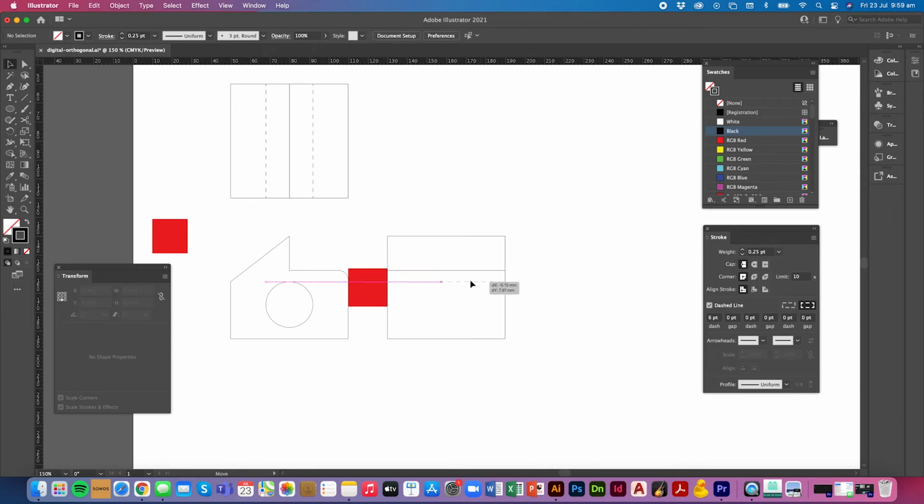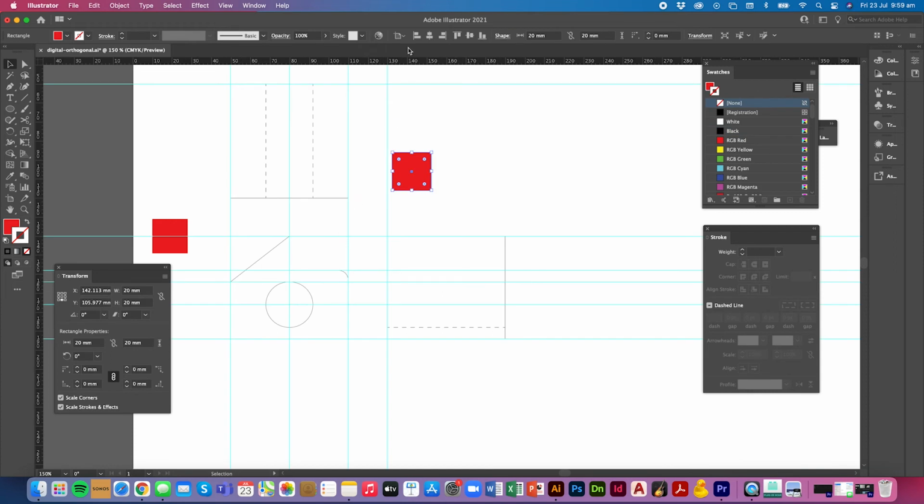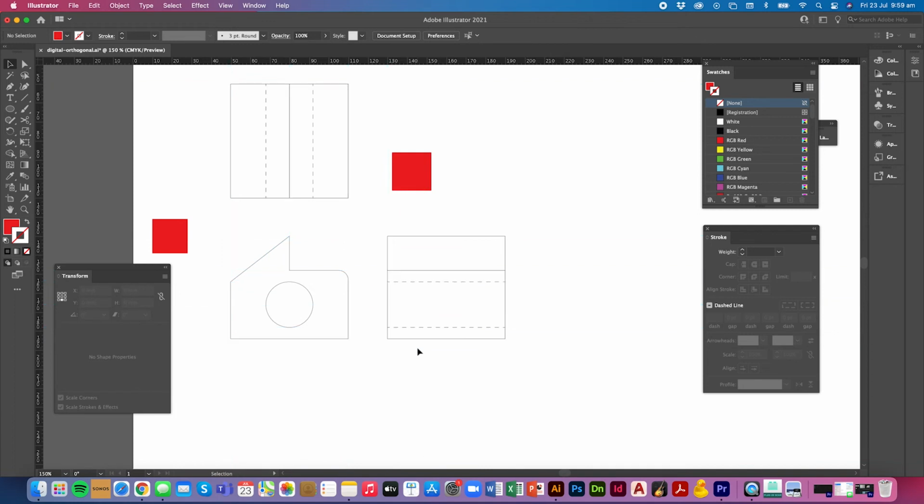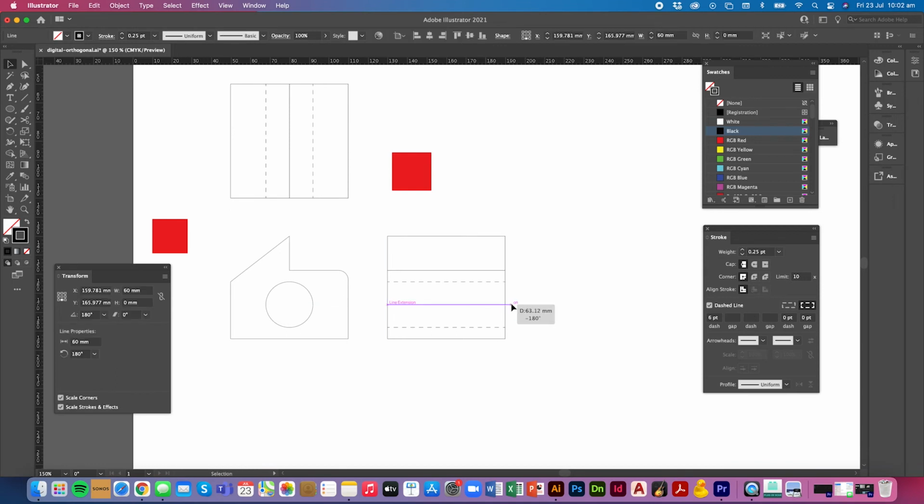and the guides in Illustrator are showing me when these things are lined up. Not there, it's not. I might need my guides back in for the bottom of the circle. Oh yes, it is in line. Add the center line, so dragging down my hidden line, making it a little bit longer so it sticks out from the drawing on both sides.